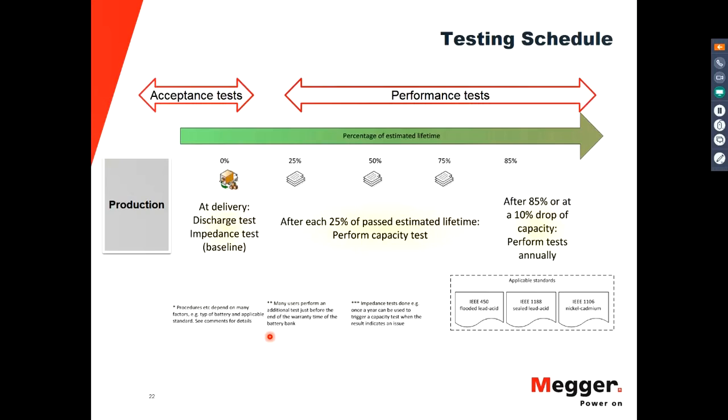Another reason that could be considered destructive is because, if you don't handle the test properly and you don't stop the test when the battery reaches the end voltage, it will affect the battery. But it's not the test itself that is destructive. If you're not careful running the test, you could of course damage the battery.